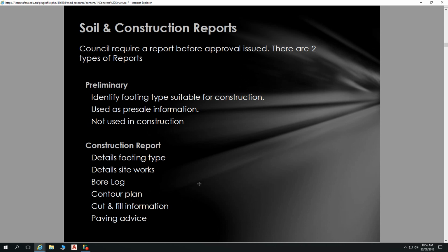We can do that with paving. We can do that with a ring of concrete paving around the building that slopes away to ensure that moisture goes away. We can think about what type of trees. Some of our eucalypts are fantastic water pumps.